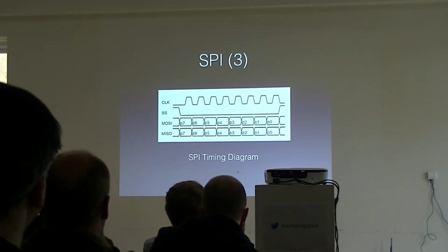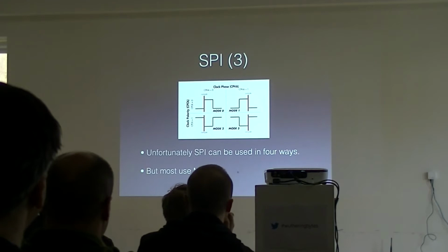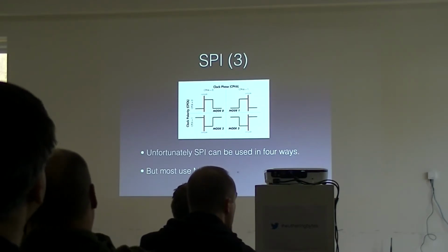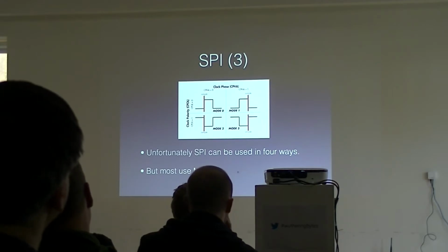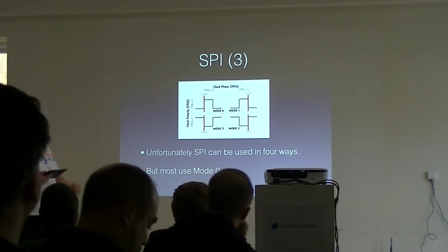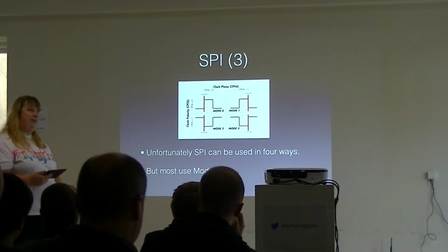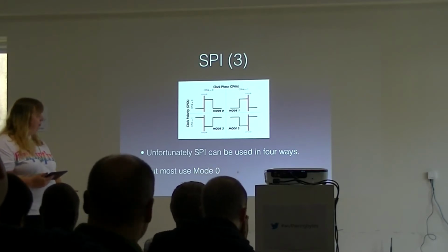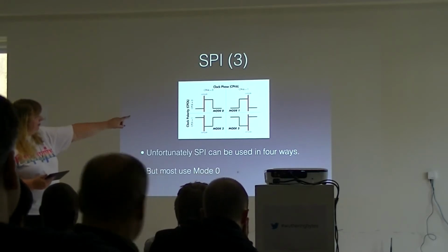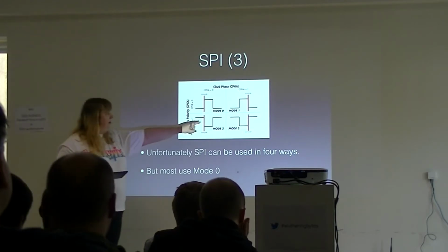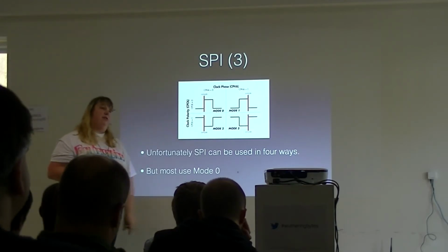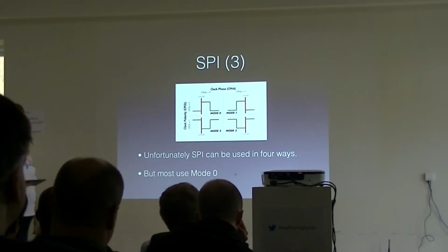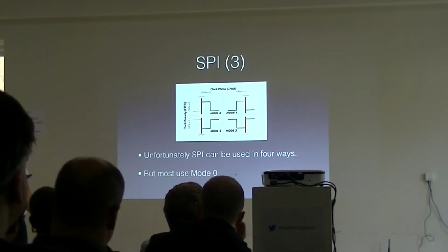Slightly annoyingly, when this was come up with, we could decide which way the clock should be and when the hardware should read the levels. So there are 4 different ways of doing it. But I've really only ever seen these ones. There are other ones, but I've mostly seen mode 0 in the chips I've played with.